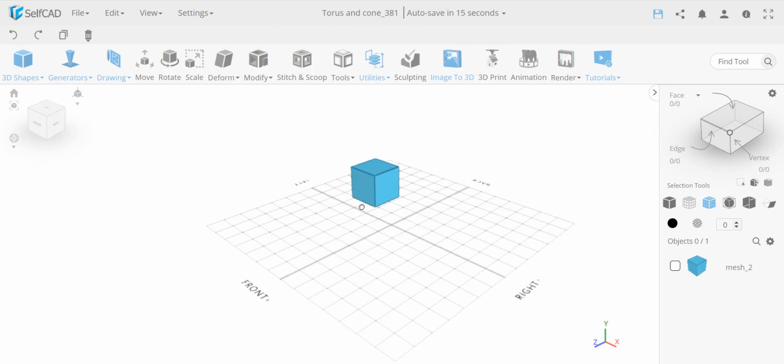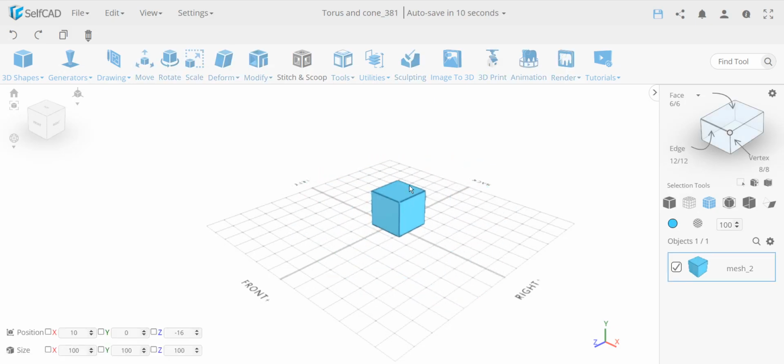Similarly, I can take an object and move it around freely on a 2D plane. That's freely. But if I want to move it up, I'm not going to be able to move it up the same way you can freely move a physical object you're holding. You have to have some helpers, and these helpers are called gizmos. And for that, we go to a tool that's called Move. I mean, you don't have to go to the tool, you can enter a position. For example, here at the bottom, we have three axes, X and Y and Z. This is how it's demonstrated.